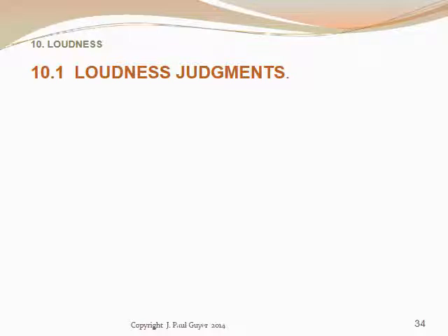Under controlled listening tests, humans judge that a 10 decibel change in sound pressure level on the average represents approximately a halving or a doubling of the loudness of a sound. Yet a 10 decibel reduction in a sound source means that 90% of the radiated sound energy has been eliminated.